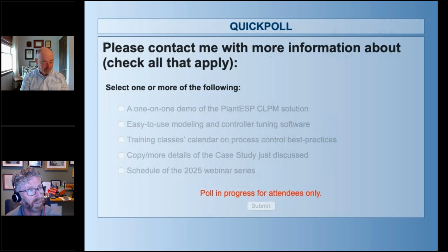Right. I love this question. Yeah, go George, you go with it first, I suppose. Well, this is one of those situations where we say, hey, take a minute, put on your safety shoes, and go look at the valve. Let's not talk about tuning and things we can do on the screen at the moment. If we have stiction, we should get up and go look at the valve.